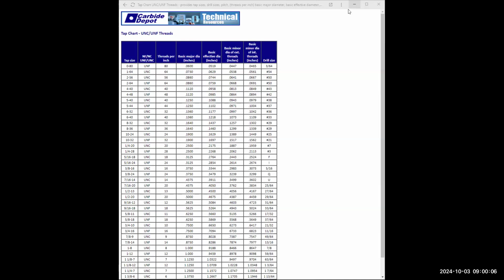Now I want to change these lines to hidden. So type in change, enter, select the lines you want to change. Enter, type in P for property, enter, type in LT, which is line type, enter, and you're going to type in hidden. Enter, enter again.